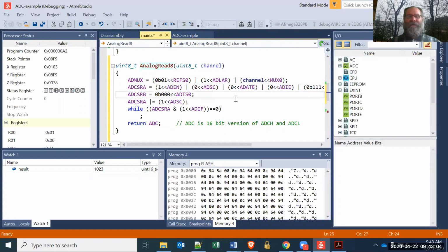The result of the A to D is always going to be put into, basically, call it a 16-bit register. It's a high and a low, but let's call it a 16-bit register. If this left adjust result is a 0, it's not left adjusted, it's right adjusted, and you get a 10-bit value. The 8 bits of the result are in the lower 8 bits, and the high 2 bits of the result are in the upper byte.